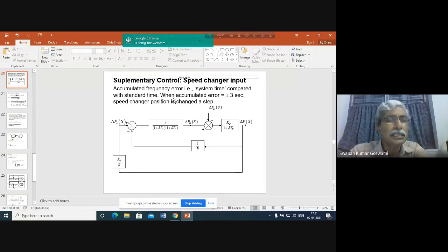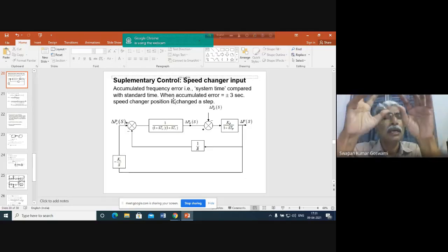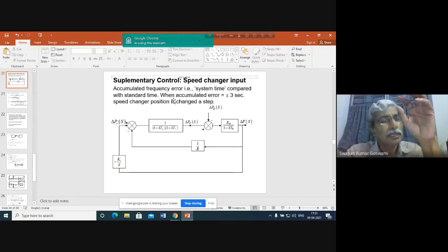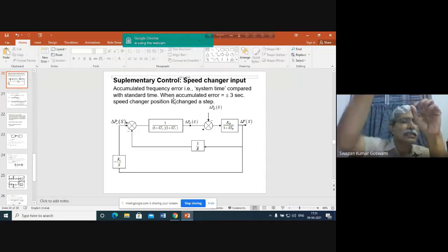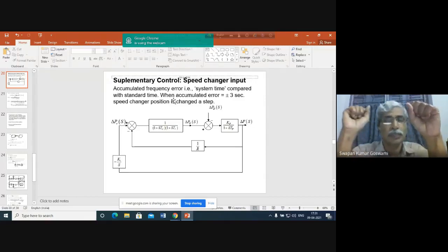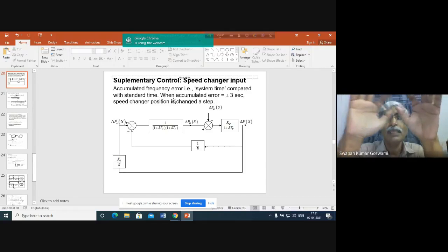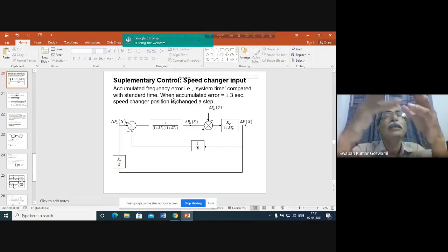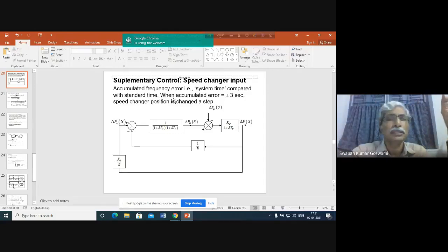And the larger the interconnection, the better the frequency regulation in any system, because more and more rotating machines and more and more inertia are connected together. For supplying any newly connected load, the power can be supplied by extracting the energy of those rotating inertia, rotating mass. That's why the larger the size of the system, that is, when more generators are connected in parallel, the better the frequency regulation. Since 2014, the total AC interconnection was complete in our system.